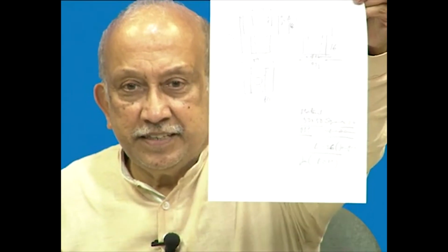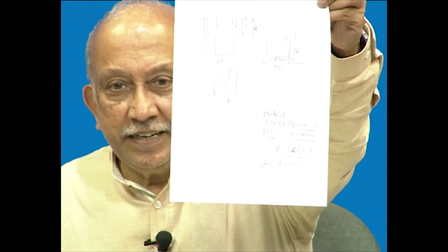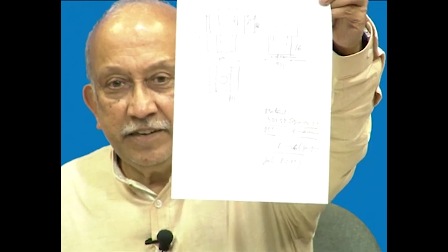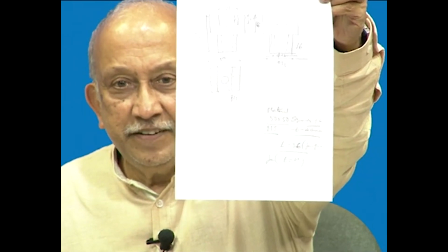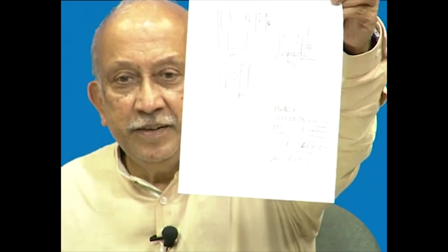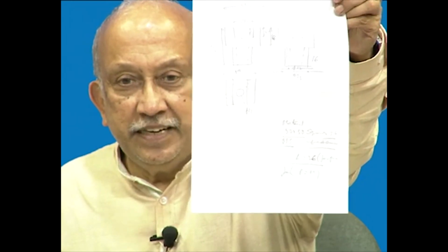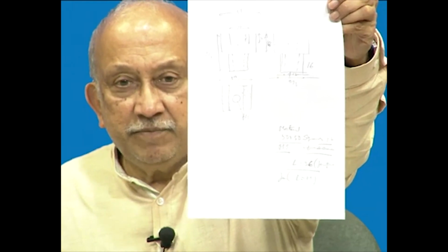and most important is at the bottom, things related to the material are written there. It says I need to take a 50 mm by 50 mm mild steel square of length 36 millimeters, though the object length is only 34. That 36 mm is supposed to be specified so that they can order stock based on this. This important right side bottom information is very much important for the bill of materials preparation.